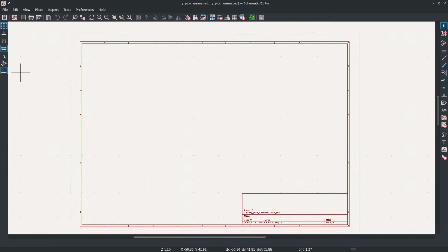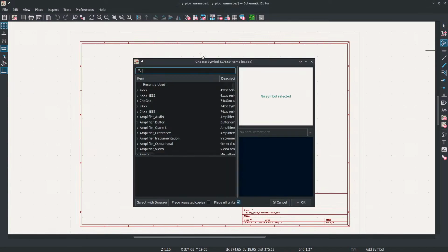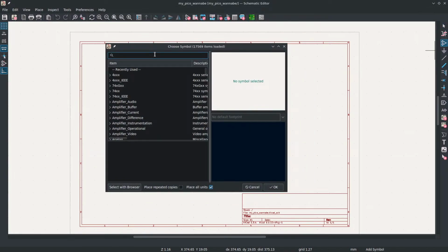So to start off here, we're going to use the RP2040 just because that's the microcontroller I'm trying to get everybody to use, so we can order a bunch of them for cheap and put all the boards together, and they're easy to get using. And the KiCad software already has a symbol for them, so we don't need to worry about making it.